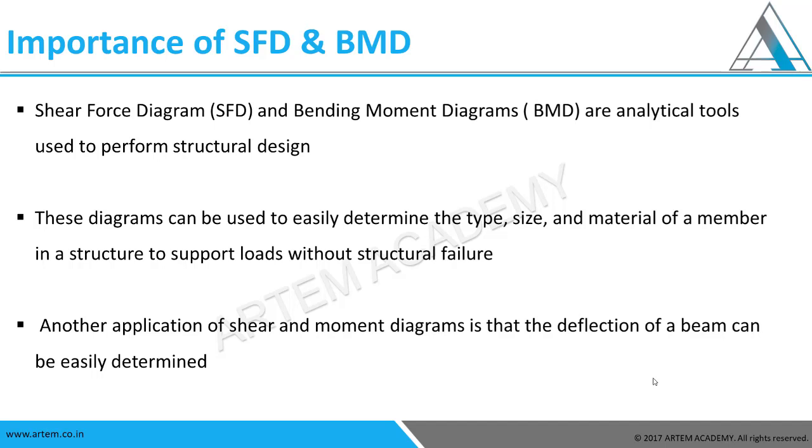Another application of shear and bending moment diagrams is that the deflection of the beam can be easily determined. You would have seen a lot of ways through which the deflection is calculated. There is the Castigliano method, the moment area method, the conjugate beam method, and n number of ways how we can calculate. In the moment area method, you actually need the BMD for calculation. So SFD and BMD are an important part of any designing that is happening on the beam. They have to be calculated, and through them the stresses have to be calculated, and through which we know whether the material will be able to sustain that amount of load or not. So it is actually very important.